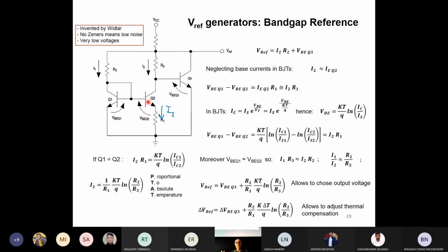Because if you heat a doped semiconductor too much, due to the thermal generation of electron-hole pairs, when the temperature is too high, you will mask the doping. So you will have more carriers generated by thermal effect than the carriers which are due to the doping. At that point, the transistor will not work anymore. So that's the problem with the temperature.